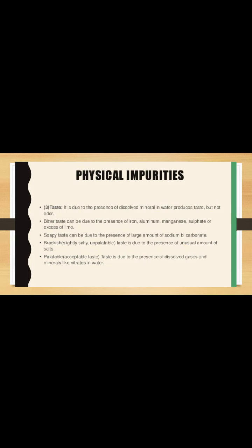Then taste. The presence of dissolved minerals in water produces taste but not odor. A bitter taste can be due to the presence of iron, aluminum, manganese, sulfate, or excess of lime. A soapy taste can be due to the presence of a large amount of sodium bicarbonate. A brackish, slightly salty or unpalatable taste is due to the presence of an unusual amount of salts. An acceptable taste is due to the presence of dissolved gases and minerals in water.